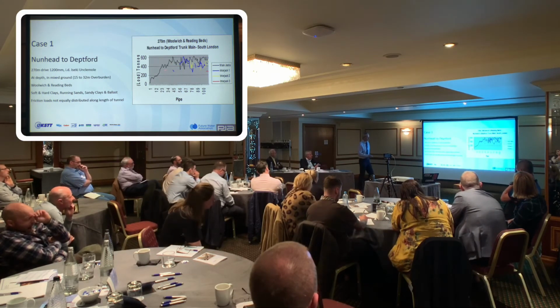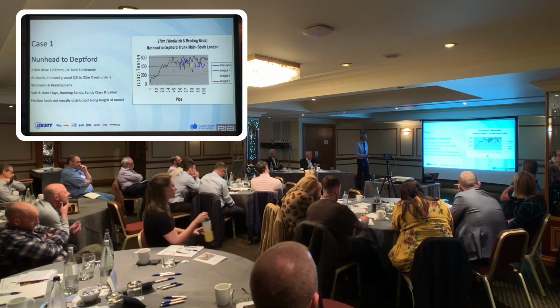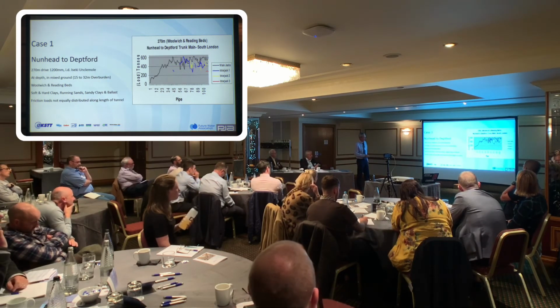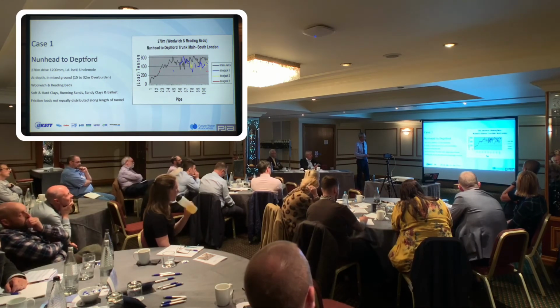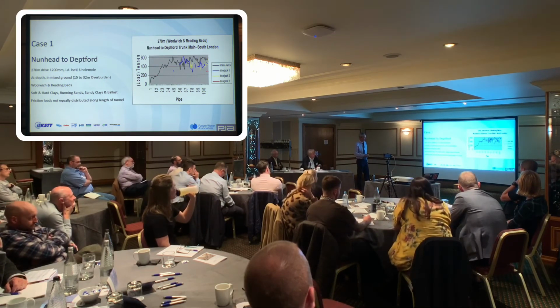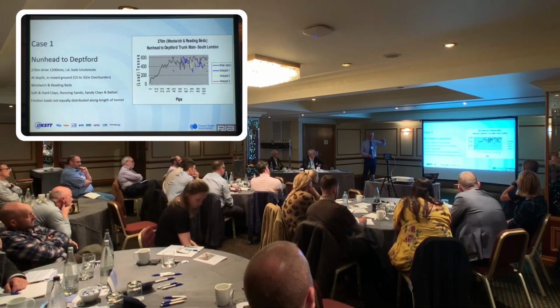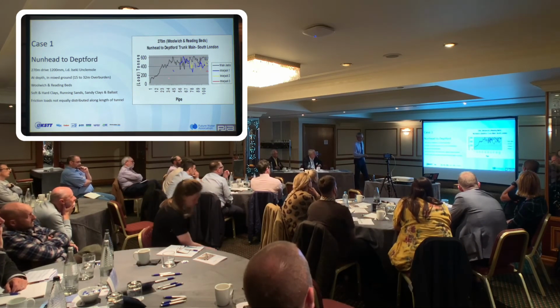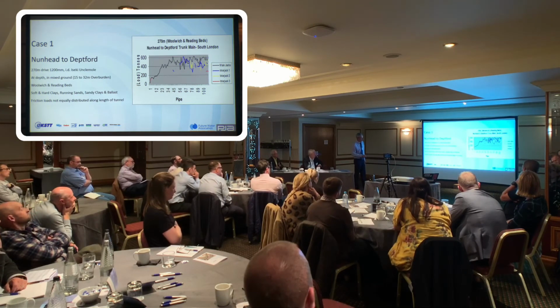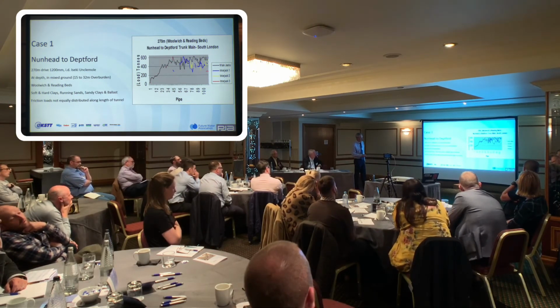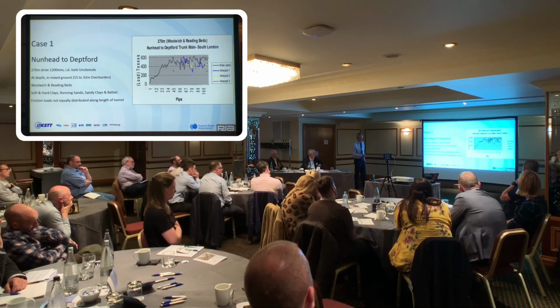So these are the jacking loads associated with this drive, and it's remarkable that the actual jacking load picture looks very similar to the ground profile picture. As we advance under the hill, the jacking loads on the main jacks are increasing, and then we come to the cutting and they go down, and then we start getting loads again.